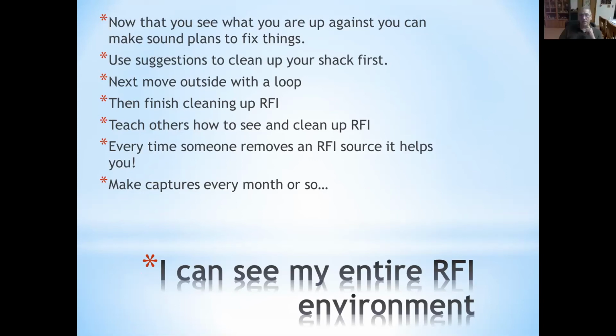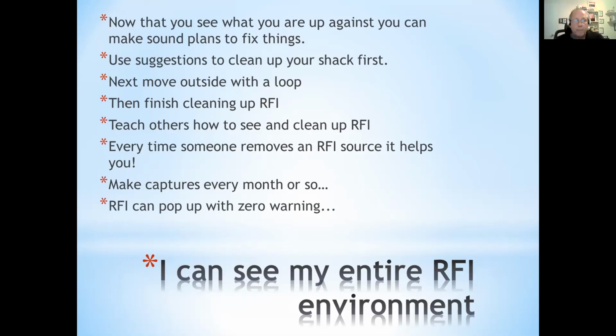That's useful for... Mike, what's that? Document your RFI background. Right. Then someone moves in with a solar system and you document the difference. It's really good ammunition for the FCC. Oh yeah, definitely. Good point. Because RFI can pop up with zero warning. I mean, I've had RFI here where all of a sudden you'll get S9 RFI, and then 3 seconds later it's gone, and what the heck was that? And sometimes you just don't know where it comes from.